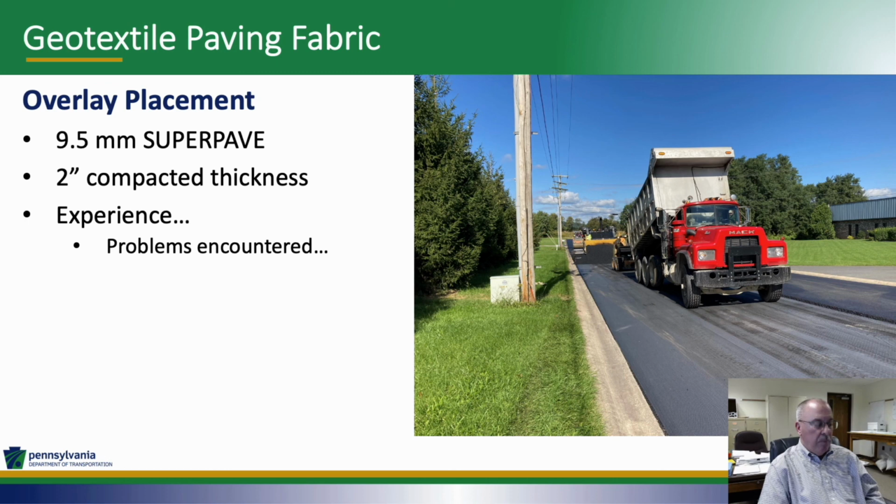If needed, you want to blot the excess tack coat that bleeds through the paving fabric by broadcasting sand on the paving fabric as the trucks pull in and out of the job. As with any paving fabric, the minimum compacted thickness of the first lift of overlay asphalt must be greater than 1.5 inches. And although we were dealing with an experienced contractor as a general and a subcontractor, we did encounter some problems as shown on the next slide.